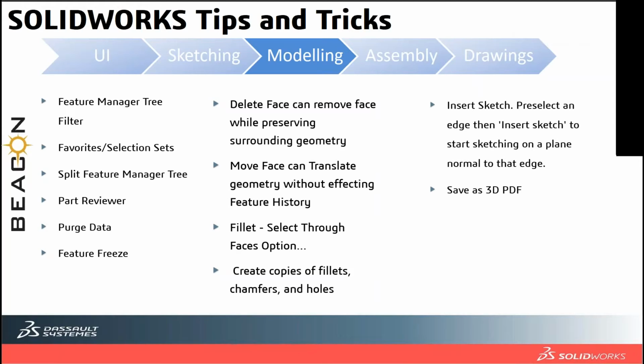And we saw delete face. We saw that knuckle wherein you need not create a circle and then cut out. You can just use the delete and patch command, and SolidWorks will patch the entire thing for you. The next thing we saw was the fillets. We can select through faces, right?